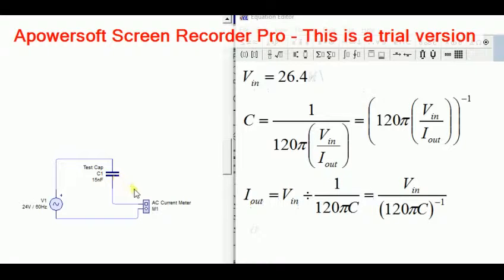One thing you want to know about this circuit: you do not want to put a big capacitor in series. Most non-polarized capacitors won't be that big, but if it's something like 45 microfarads, it might overload the power supply, the wall transformer, and cause a short.